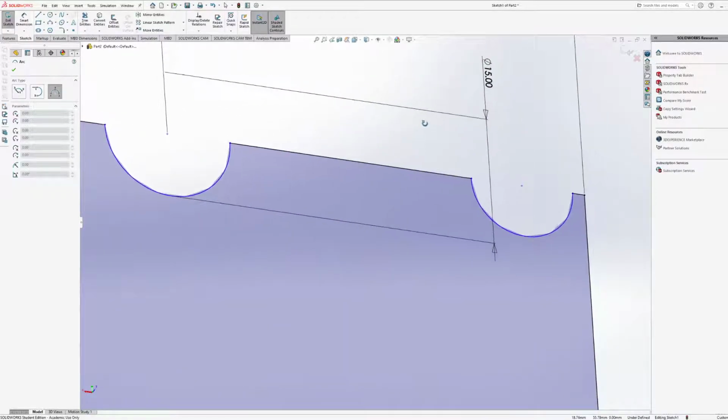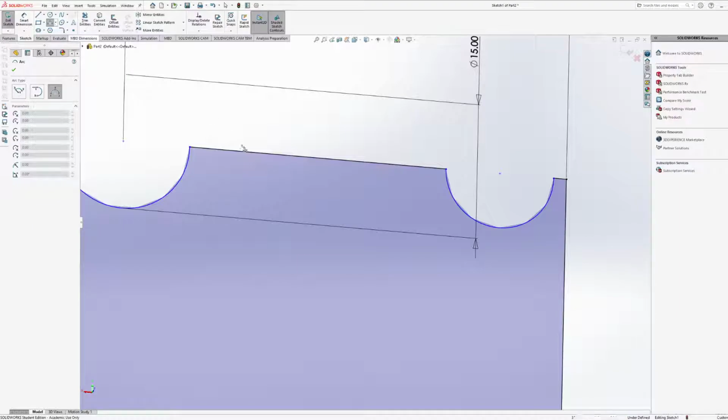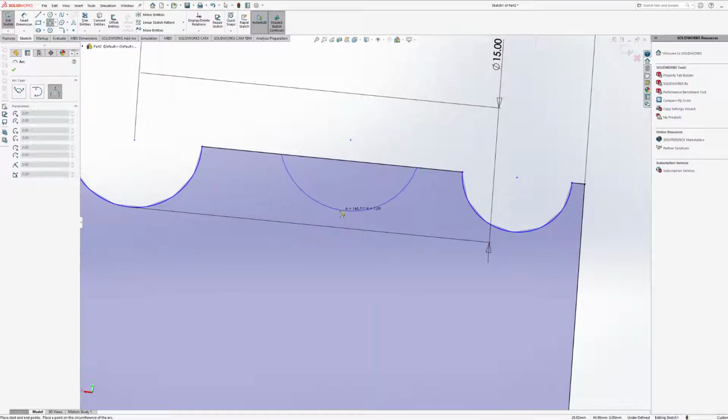But you can use any one of these options to do it. So if we're using the 3-point arc, I would just select 2 arbitrary locations, and this is basically going to determine the diameter of the circle. Or rather, it could be the diameter of the circle, I guess I should say. It's only going to be the diameter if you align it correctly, such that the center dot, it's hard to see, that little plus sign, is right in between the 2 points.